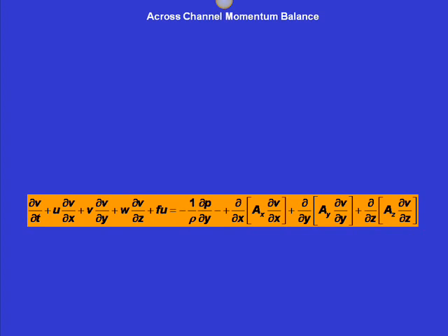So again, as I was saying, we're going to study now the momentum balance in the across-estuary direction. So in the context of our classroom, in this direction. So what would you think happens? Well, first let's look at the lateral momentum balance. Conceptually, let's try to think what would happen to this estuary flow. Let's suppose that we have near surface outflow and near bottom inflow. What's going to happen to this vertically sheared exchange flow across in that direction? What do you think the momentum balance is?